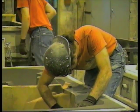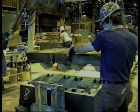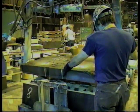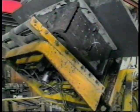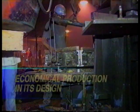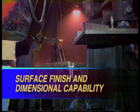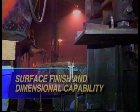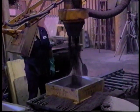In regular steel casting production, the pattern is used to make a mold. The mold holds the liquid steel in the correct shape while it solidifies. While the mold is used only once, the pattern is used again and again. Important considerations in mold making include economical production in its design, surface finish, and dimensional capability. The most common material used in mold making is silica sand. The sand must be mixed with a binder to hold the right shape.